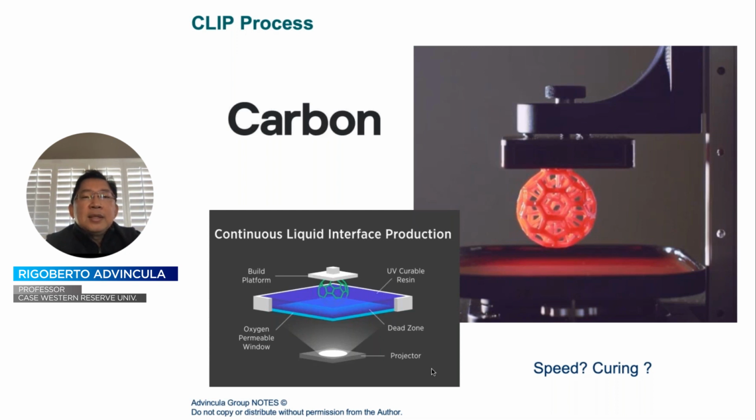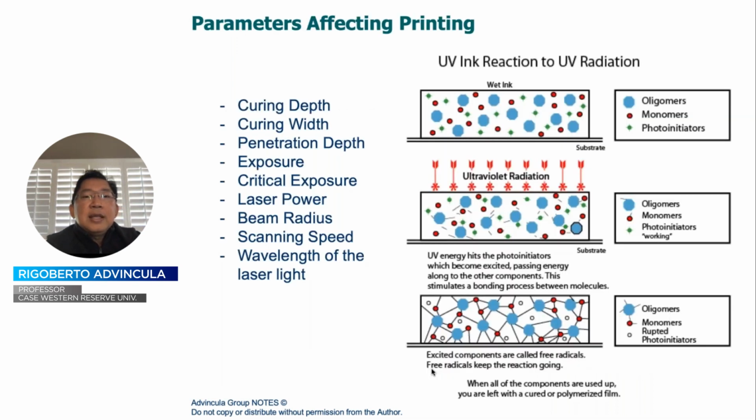And one has to pay attention that a lot of these processes, including the clip process, require a post-curing or optimization technique in order to get rid of the uncured material or monomer, or sometimes require washing to remove any type of unpolymerized material. But nevertheless, maximum strength, and this has been proven again and again, is obtained by a type of post-processing, UV, thermally driven, or even requiring some bath techniques, to obtain the best thermomechanical properties. So it can be quite controversial whether this step actually makes the process slow compared to other 3D printing techniques.